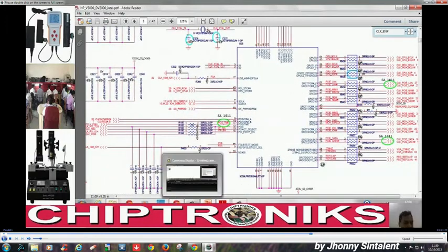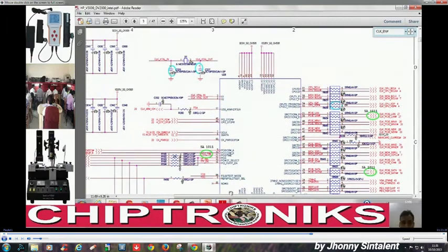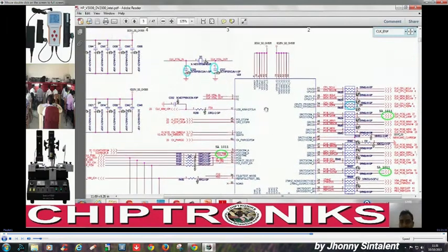This is generated by the clock generator. Now, what are the important points when we are checking a clock generator? First, supply, crystal, STOP_CPU, and CK_power_good. We can check this output pin through a CRO. It will give a sine wave having a frequency of 48 megahertz.